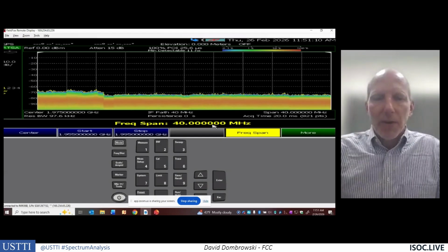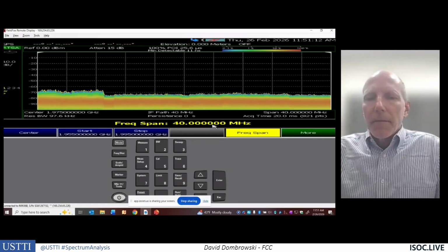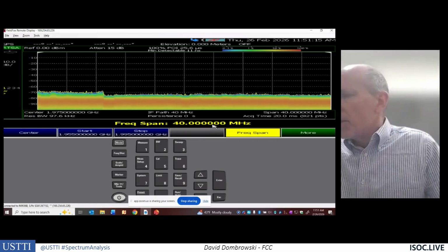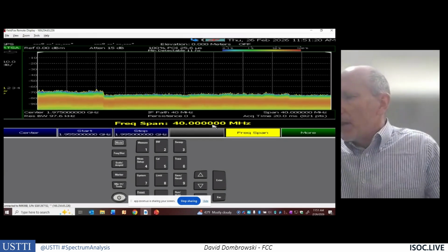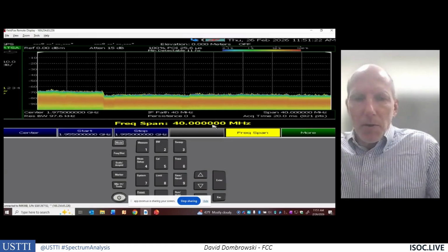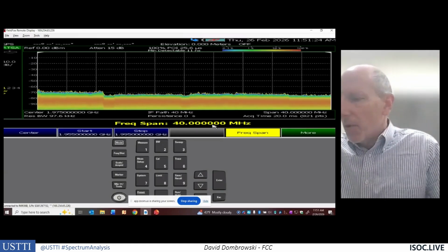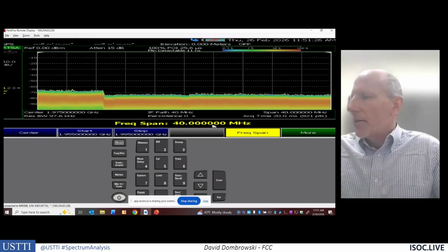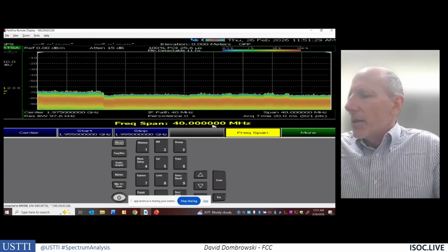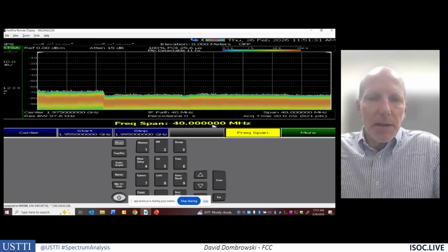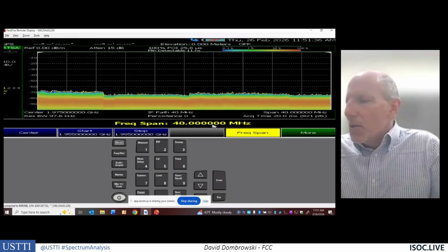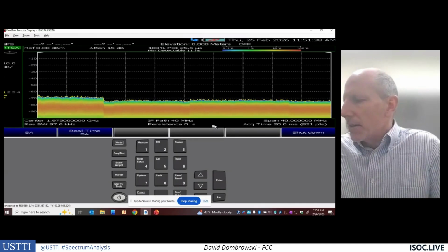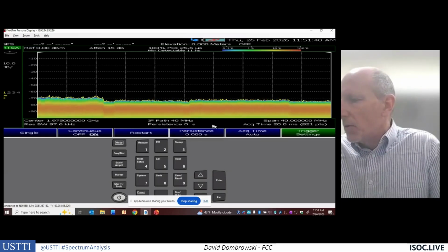This is the entire bandwidth of the real-time analyzer. So we see a couple of different LTE signals here that are rapidly fluctuating. This is called the persistence mode or real-time mode. And it's interesting. It helps us in the real-time mode. We have a high probability of intercept, and also in changing the persistence, which I go to here under sweep.